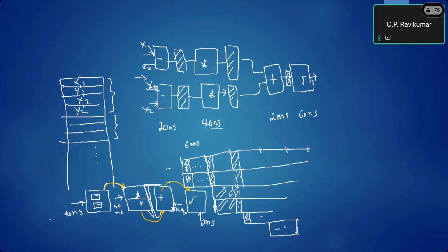Okay, so this is also one way of organizing. So we have independent modules. In pipelining, usually we do one clock. Okay. Whereas this one is slightly different. They are operating independently at different clocks, right? And they have to use some sort of a handshake mechanism to communicate with one another when they have results. Okay.